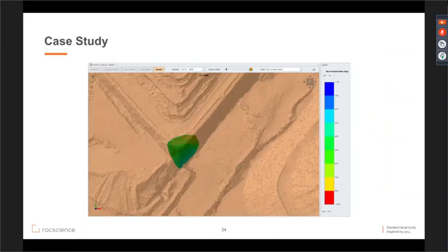First, I'm going to add a new material and rename it block model. I'm then going to select block model from the failure criterion drop-down menu and select new function. I'm going to rename this new function, for example, August 2021, if it's a current export from your geological modeling software, and then import block data.